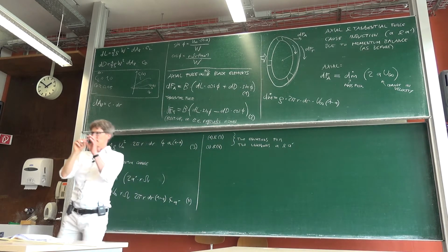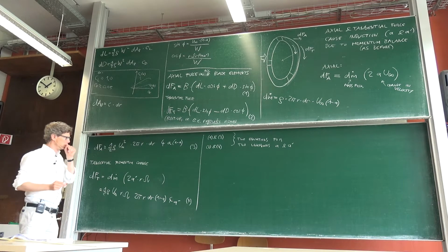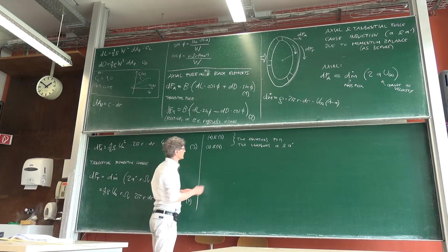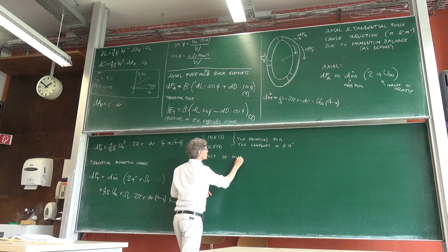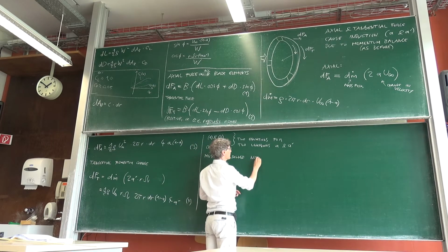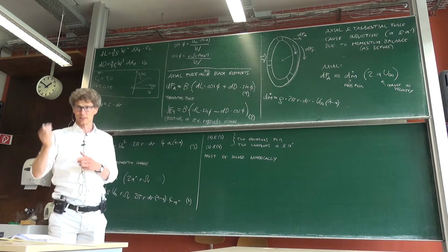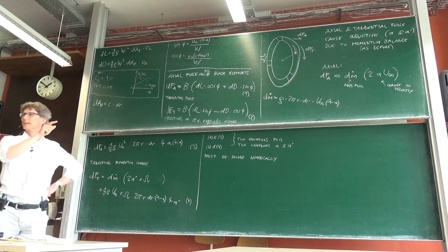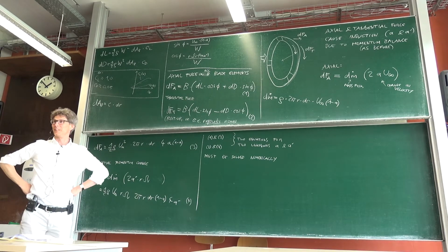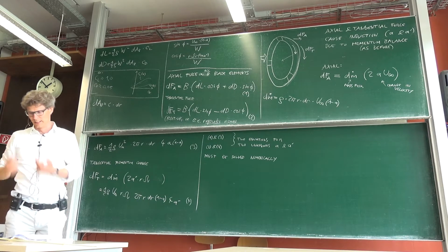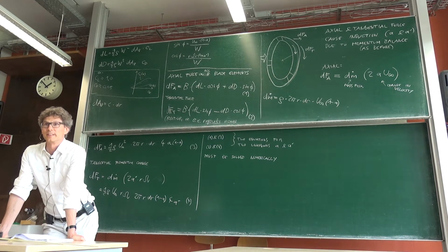And of course, this is an implicit equation. At every different radial position, it will be different. And this must actually be solved numerically, so I cannot just do it on the blackboard. It's very complicated because everything depended on a and a prime at the beginning, so it's a very complex dependence on all these things. But the number of equations matches the number of unknowns. So we don't know how the flow will actually be influenced by the wind turbine, but we know two equations that describe it.